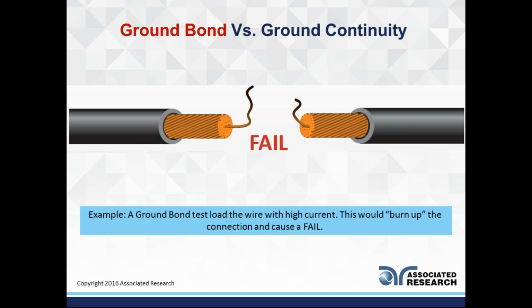The wider we make our wires, gauge-wise, the less resistance they'll have. It's like a highway. The more lanes, the wider that highway is, the less traffic we'll get. Whereas with a one-lane highway, there's going to be a large amount of traffic, or a large amount of resistance. So using Ohm's law, if I'm giving constant current, if my current value is the same but now my resistance is higher, that's a large amount of voltage. And something like this one strand just can't handle that type of current.